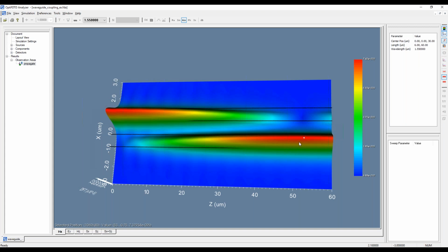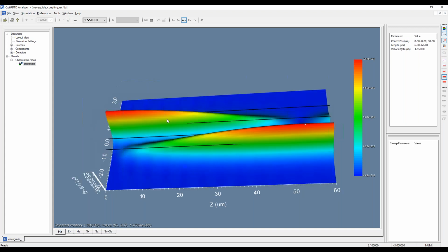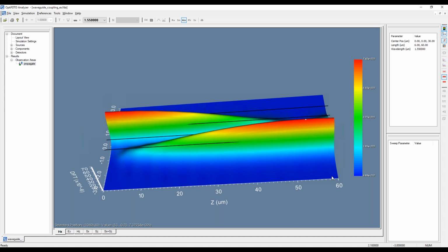And that's how they do X couplers, or cross couplers, I should say, and power splitters, as you saw in the BPM webinar earlier this year. And this is basically what we're going to do, but obviously the structure is a little more complicated. And another reason why we're not going to do an FDTD is because you can see here that the length of coupling can be pretty long compared to the wavelength, right? 60 microns compared to the wavelength of 1.55.